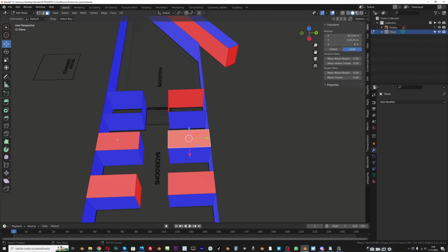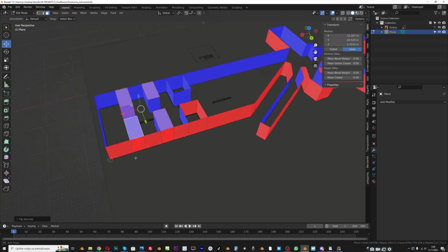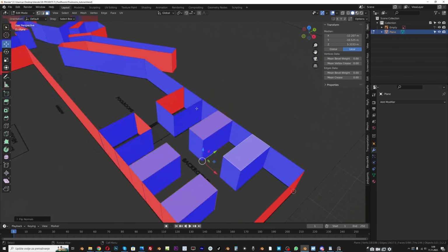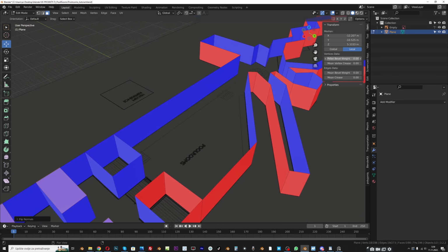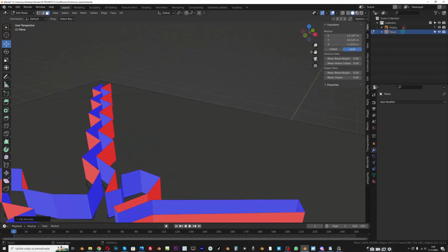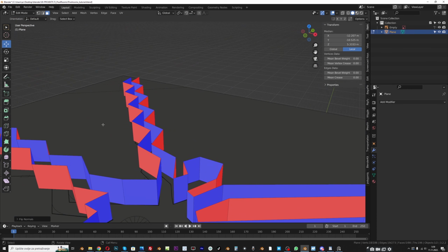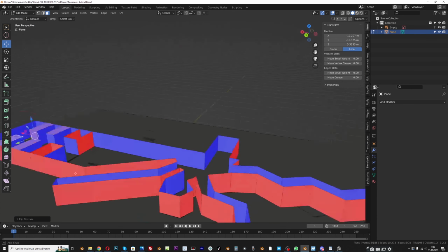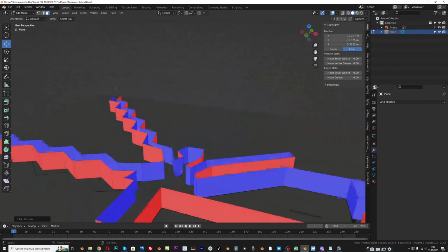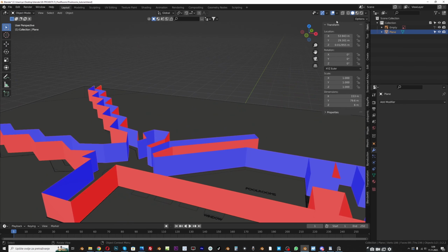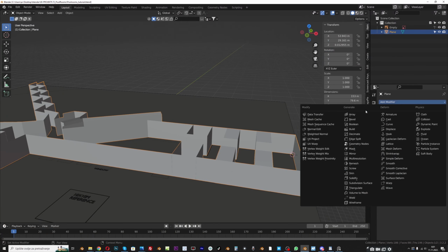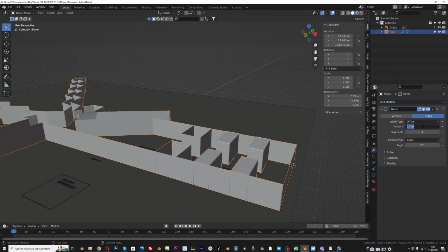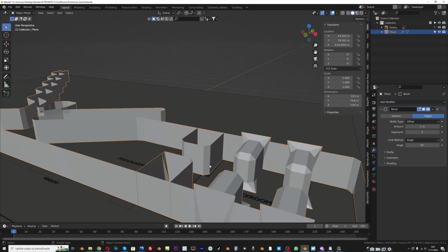And this part here is not visible in the camera, but I will also flip this. So just flip these normals, and everything that is visible in our camera must be blue. Okay, here is all blue inside, and this looks correct. And I will now just turn off this face orientation here. And now we can bring back our bevel modifier, and if we add, for example, 1 meter here, we get a 1 meter bevel.